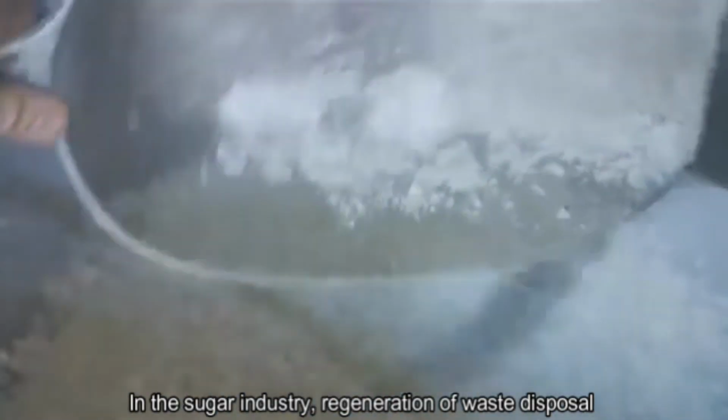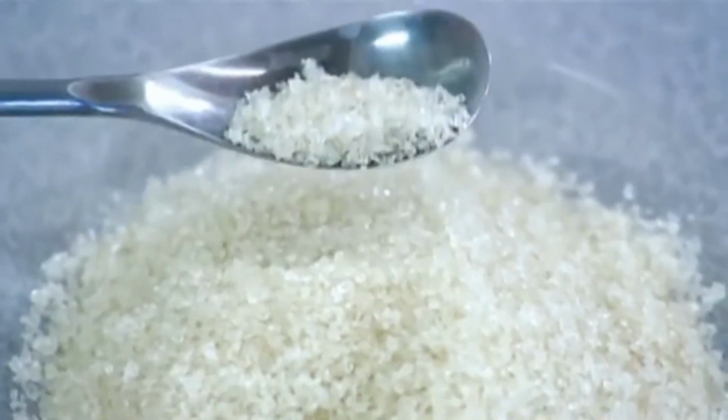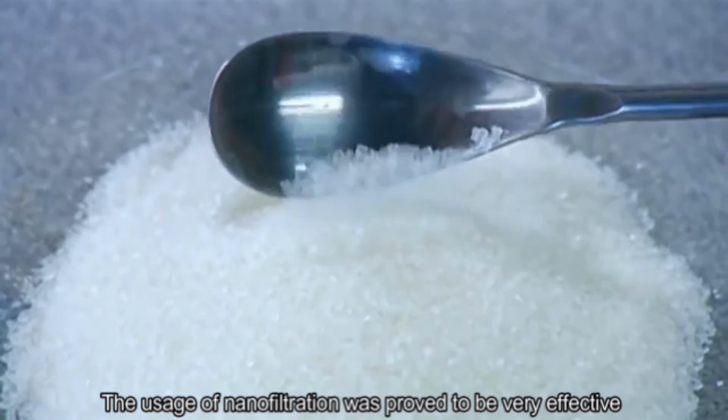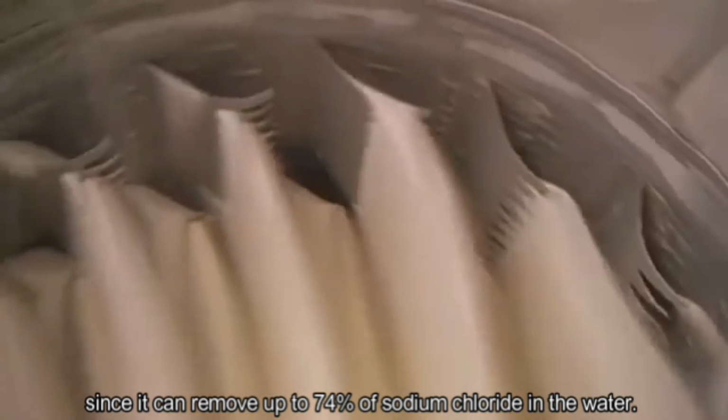In the sugar industry, regeneration of waste disposal is difficult due to the increased amount of sodium chloride and colored organics contained in the regeneration effluent. The usage of nanofiltration was proved to be very effective since it can remove up to 74% of sodium chloride